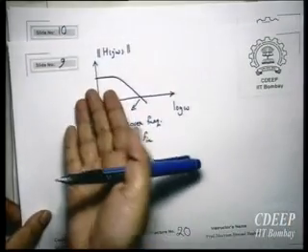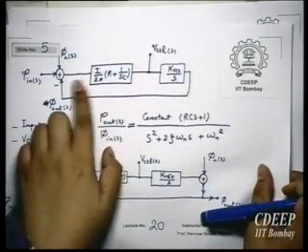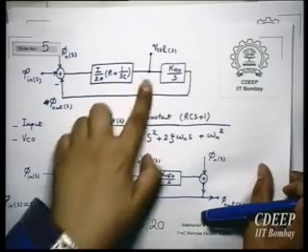Therefore, I have a limited value for the delta phi at the input. At the same time, I am giving this delta phi to the filter, and I am extracting the DC component of this. Suppose I have a delta phi, it's a DC value also, and therefore it is given to that filter. Effectively, that filter at low frequencies, which has this transfer function, has some gain. At DC, if I give a DC, I will get something here. In the case of a charge pump, actually it will be infinite, right?